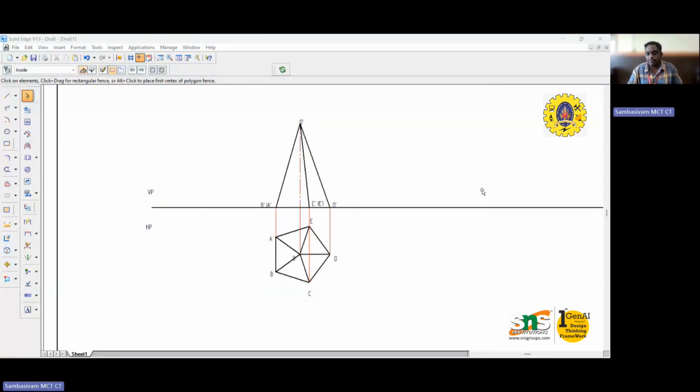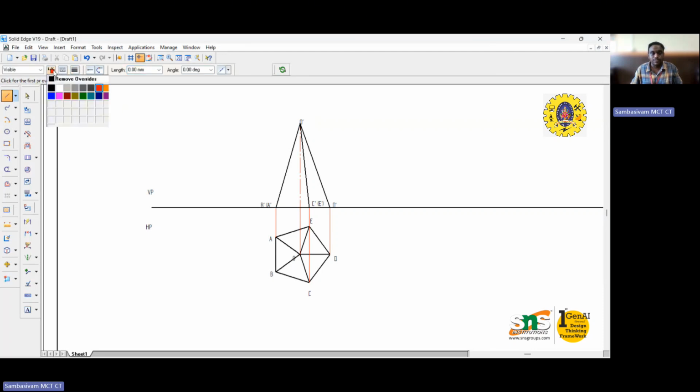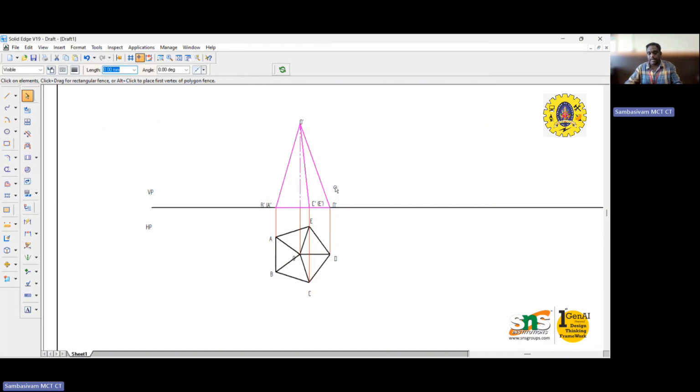So this is the previous diagram we have drawn. From this video, I would like to draw the trace lines with a dimension of 0.13 with different color patterns. Now I am going to use pink color. Before that, I would like to make a copy of the inclined portion of the top view from this one. So I select all the views which represent the diagram.